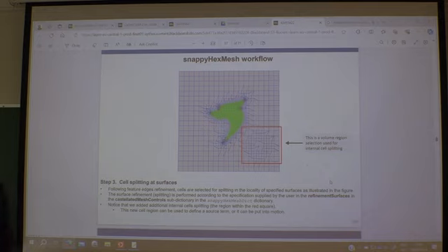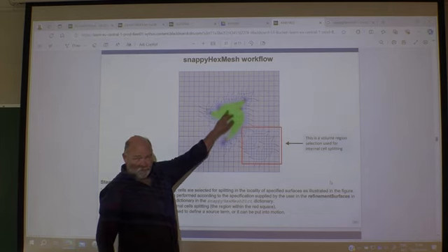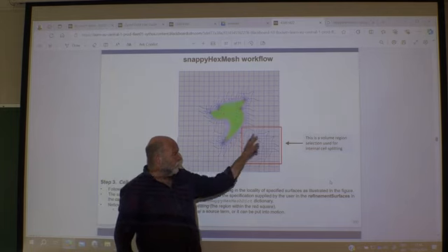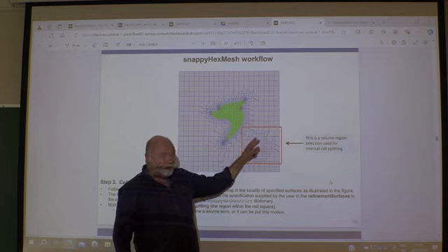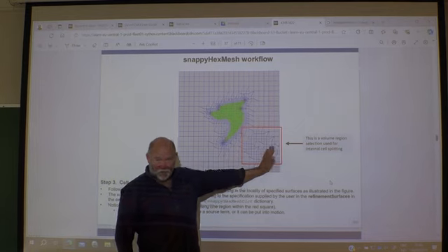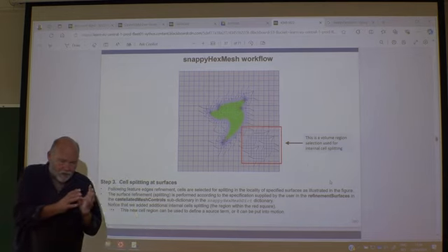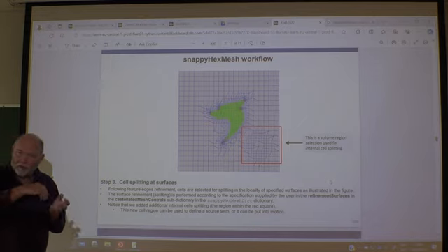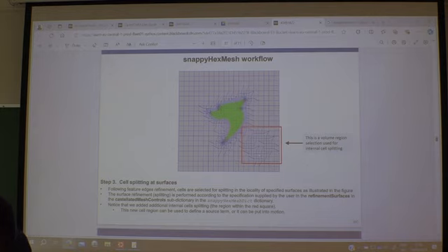Also here, for fun, they have the geometry here solid. The flow should go around this object. But here they have created a circle and then told snappyHexMesh to resolve this circle. But the flow is going to pass right through it anyway. That's also an option. If you really have a region, say, I want to resolve this region in my domain, it's very important, I know I'm going to get high gradients there, I need it to be better than my background mesh. Then you can do stuff like that.